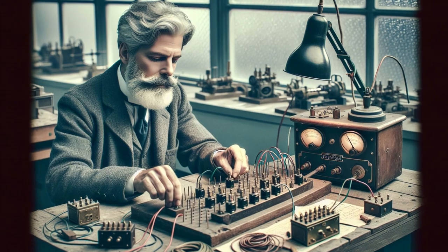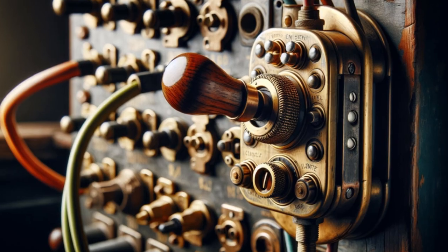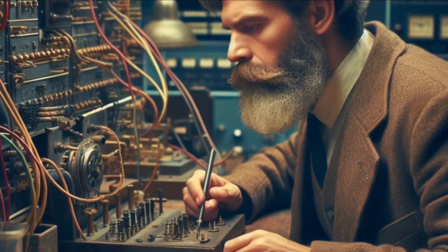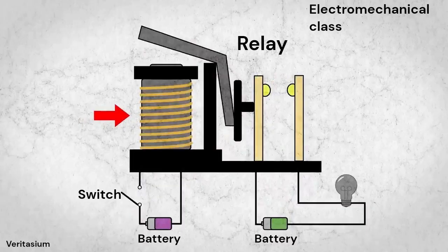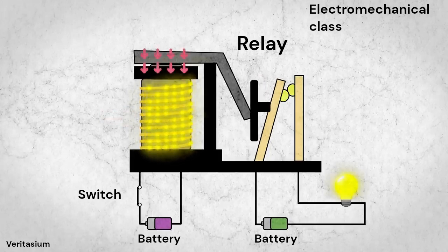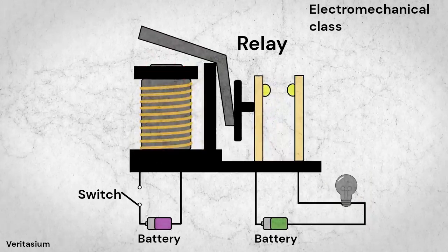New switch ideas are common and inventors never seem to sleep. Another approach relies on electromechanical techniques. There are a wide variety of methods. The relay is a prime example. All relays have at least one electromagnet. This is a coil of wire around a soft piece of iron. When current flows through the coil, the electromagnet attracts a flexible metal arm and this opens or closes electrical contacts. When the coil current ceases, the contacts take their home position.